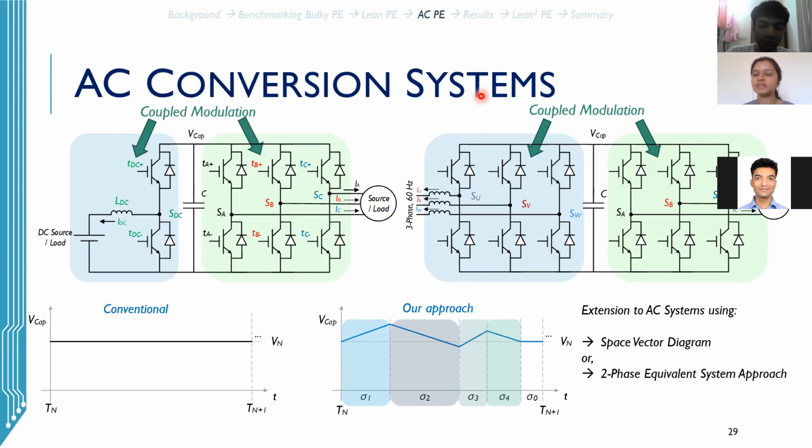Okay. So one is regarding that. The other thing is, for example, when you have DC input and three-phase output, the power flow may get balanced out, but still you will have some ripple that is flowing through the cap. Right. And what is your opinion on the current ripple capacity of the DC bus cap that is required? Because many a times it is not the voltage ripple that is the determining factor for sizing the DC bus cap. Exactly. It is also the ripple carrying capability.